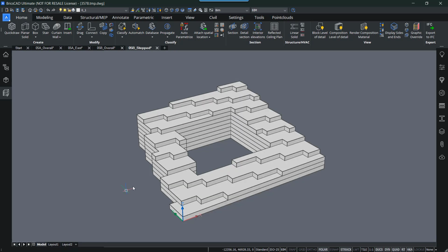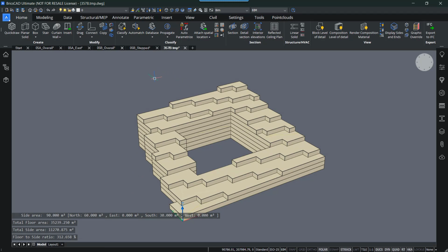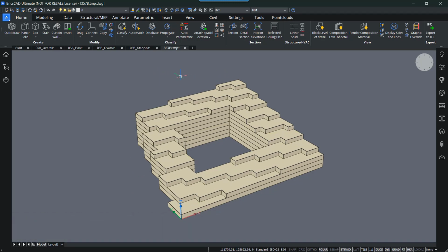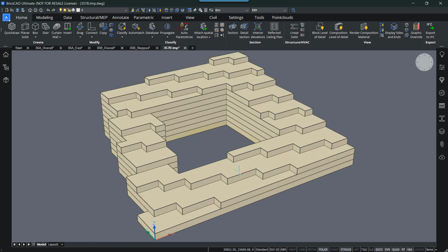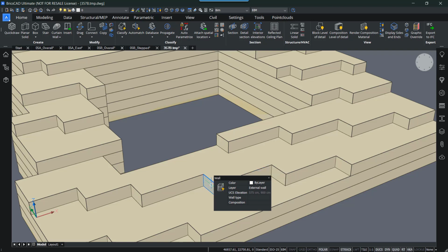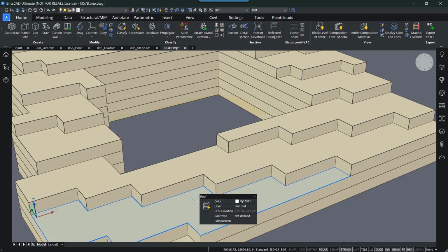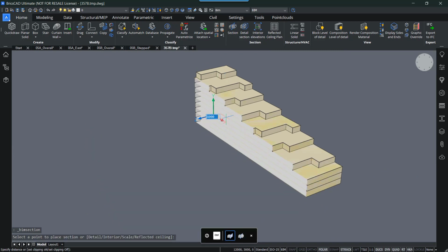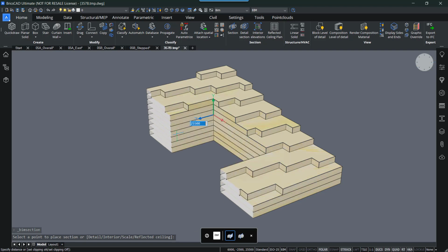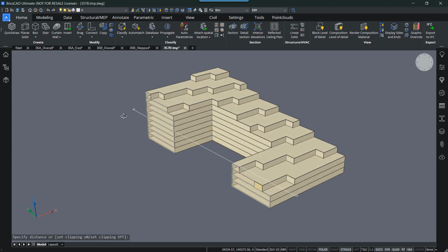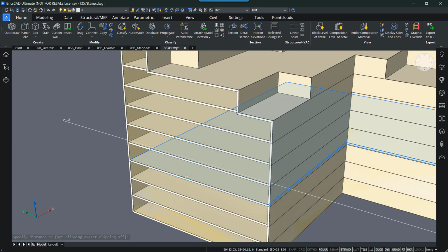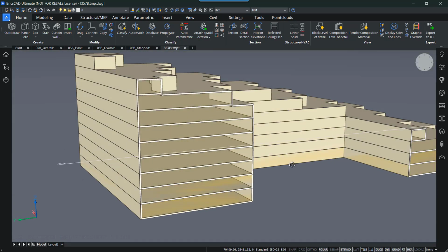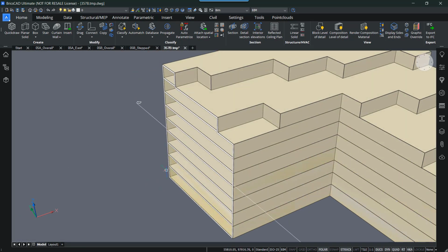And then now, as you can see, another file has been created with the same geometry, but as you can see now, everything is divided up in walls, rooftops, floor slabs, and so on. So if I now open up a section again, maybe something like this, you will see that it's hollowed out, and each and every floor has a different floor slab. Everything is nicely created with a floor height of 3,000 millimeters.